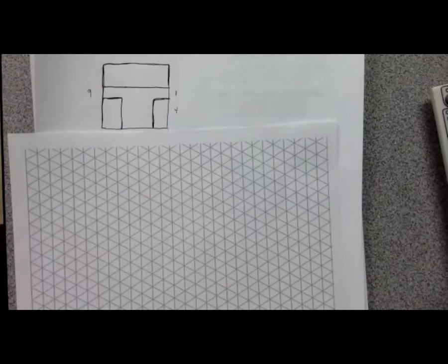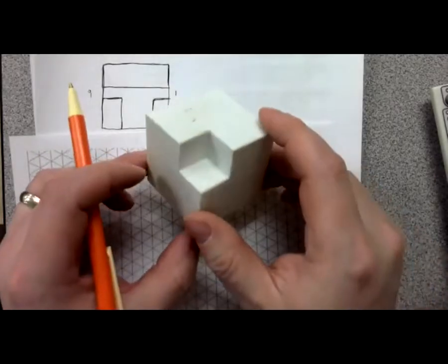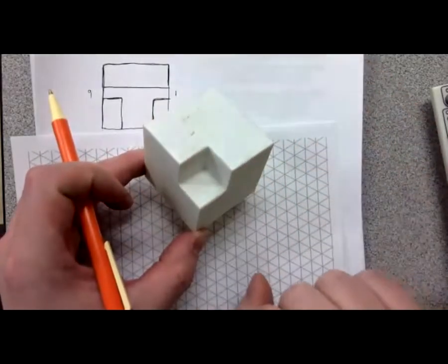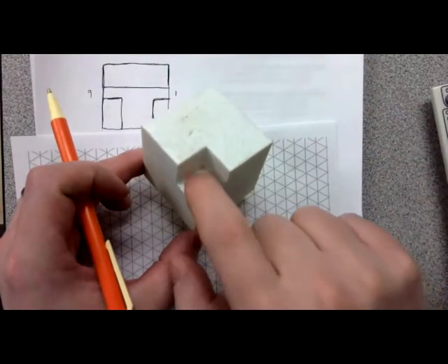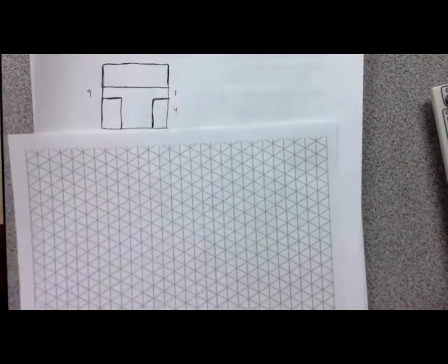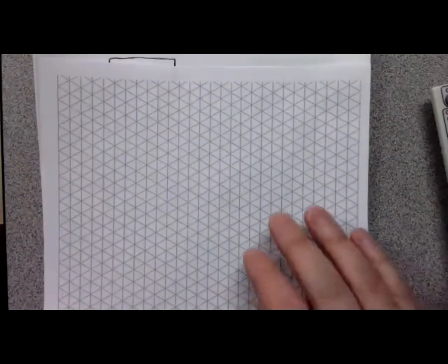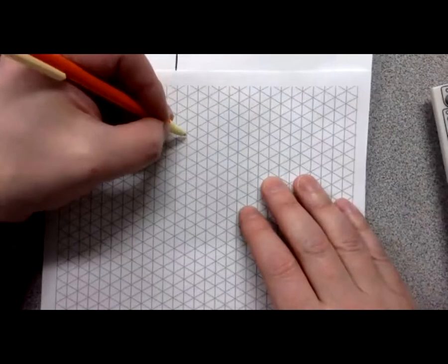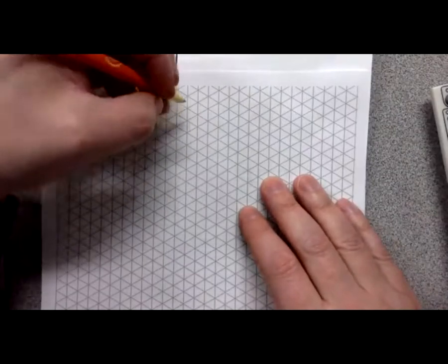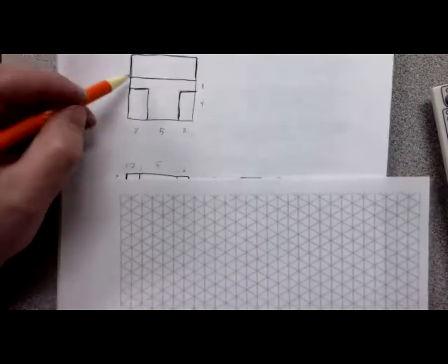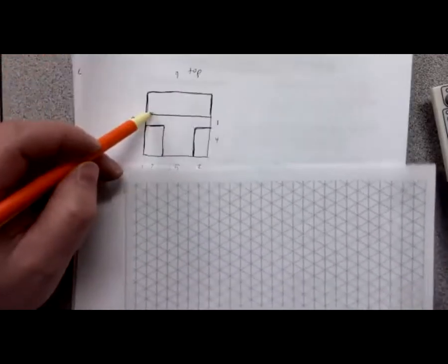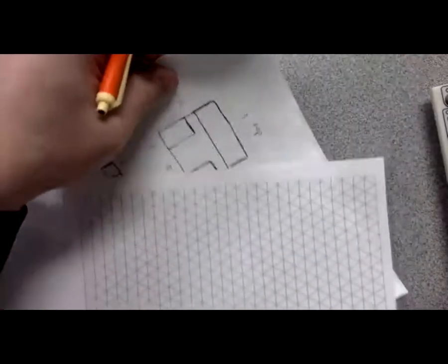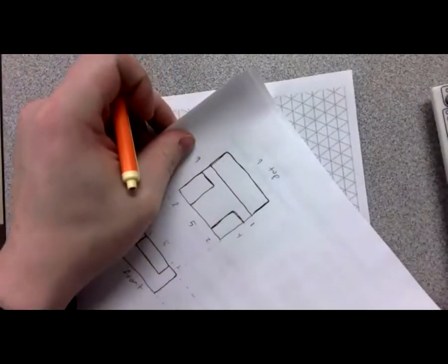Think about it as if I was making it in a wooden block. If I wanted to make this guy, I would draw the whole big block roughly and then draw this section cut out of it. What that means is you either draw with a pencil and erase, or if you're drawing with pen like I'm going to do here, you just have to be very light in your initial drawing and then very dark in your final drawing. Either way works. So if I draw this top projection on this isometric grid paper, it's going to be laid in here about like this.